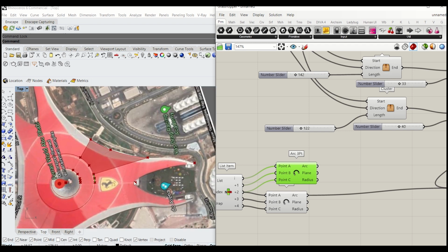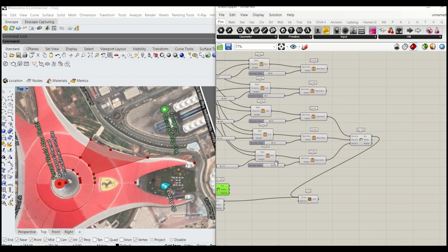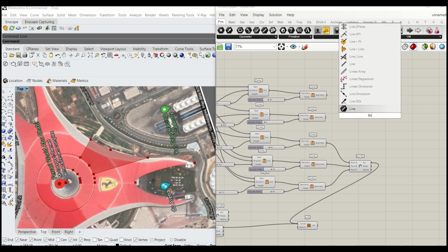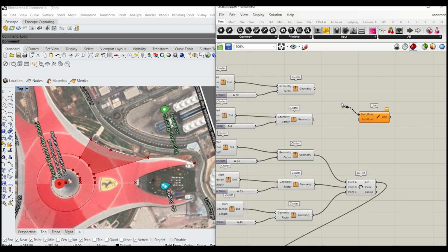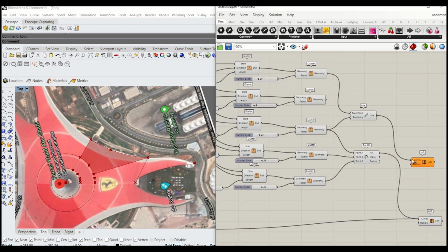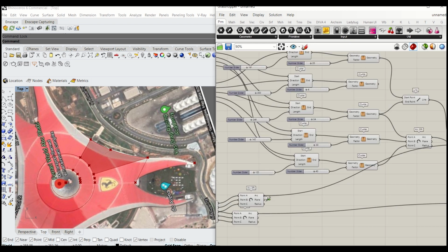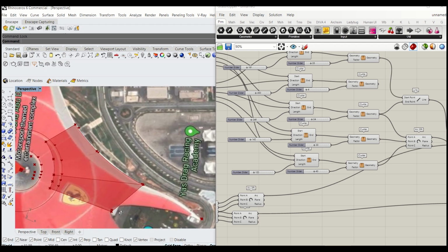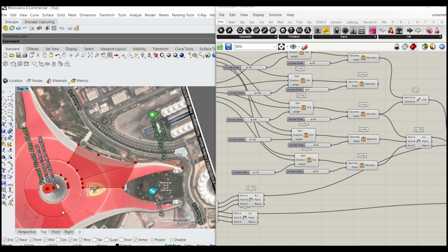So now we need to get these two connected, and we build that complete section. So we know that's third and fourth. So build line, type line between 2 points, so starting and end point. So that's the line there. So let's loft it again. So type loft and connect there, and also that arc goes there. So we now got the complete shield of 1/6 of the Ferrari World.